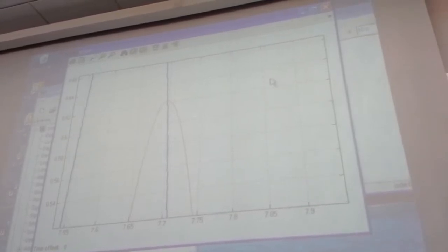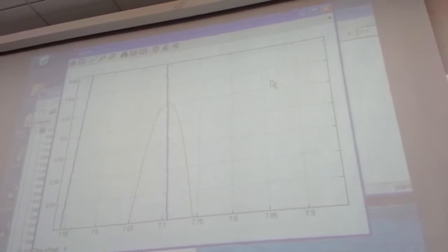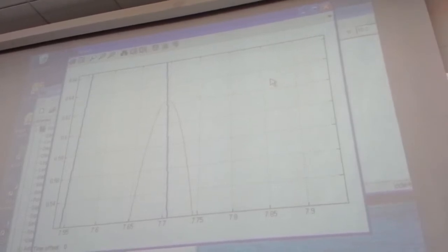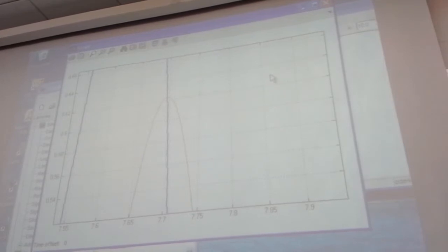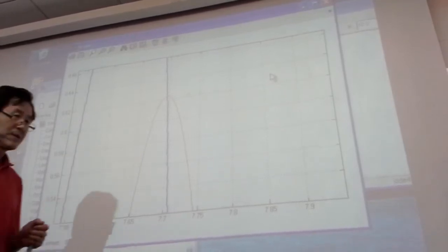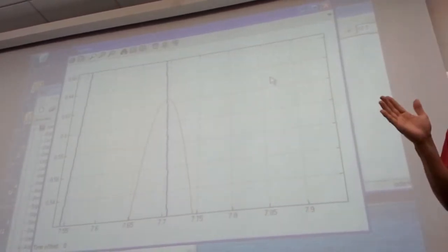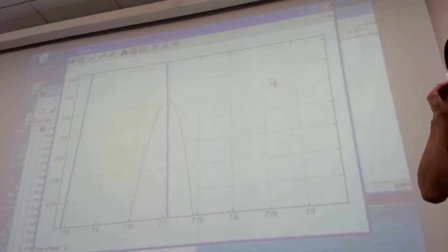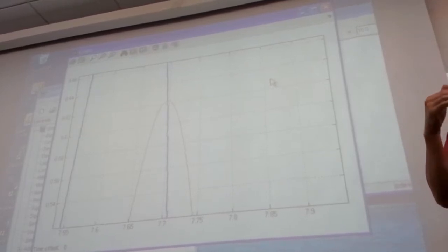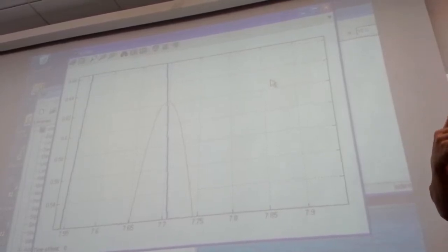Before it was 0.8467; now at 2 hertz it will be 0.622. On your original graph I didn't see it, but on ours the very first phase of the output is slightly higher. That's a transient, and you should not look at it. So if you have the frequency response, always look at the steady state.